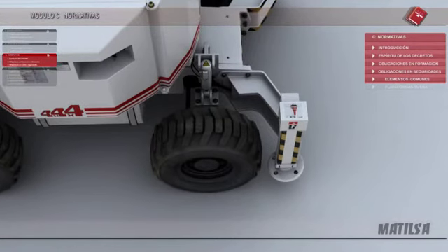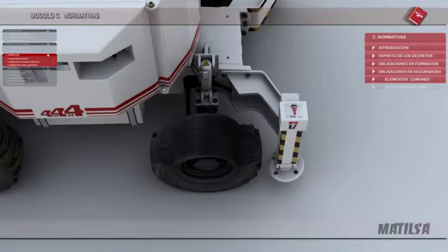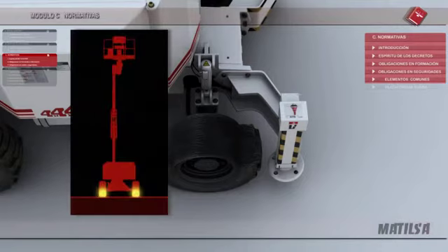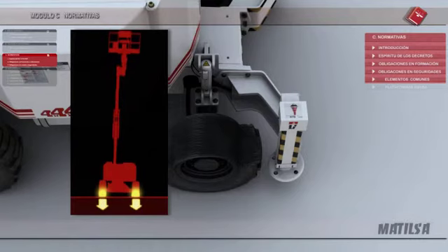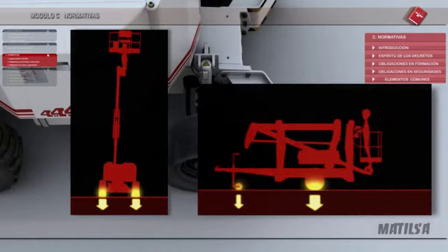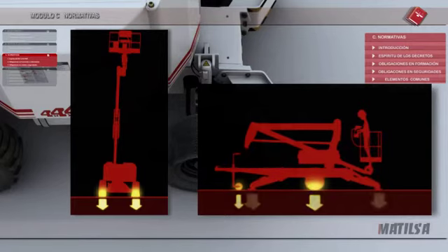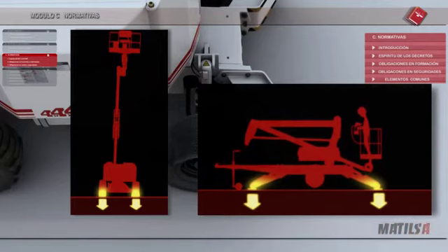Sturdy or filled tyres. The tyre will have to be sturdy or filled with polyurethane foam on the self-propelled machines. This is in order to avoid a puncture, causing the machine to overturn, which may cause a worker to fall if being transported in the elevated position. However, the machines that need hydraulic stabilizers when elevating do not have to carry sturdy or filled tyres. Examples of such machines are the trailer or truck mounted ones.